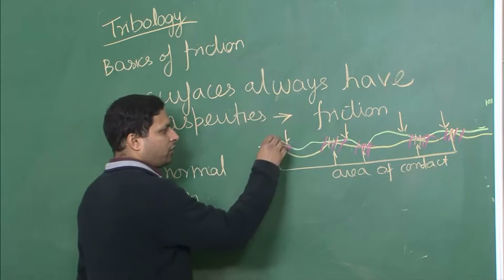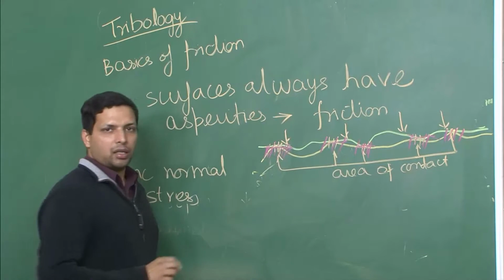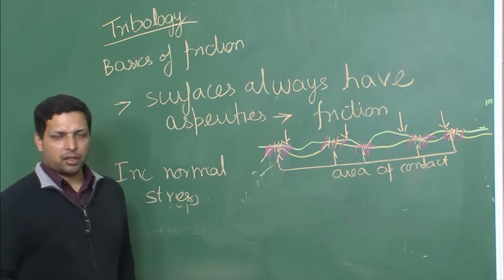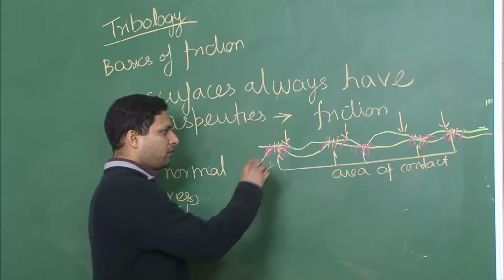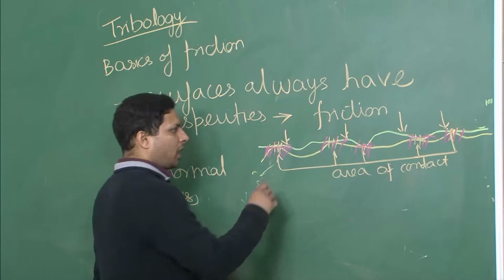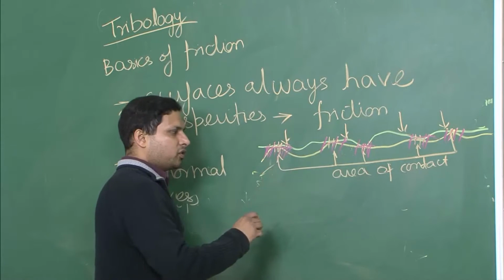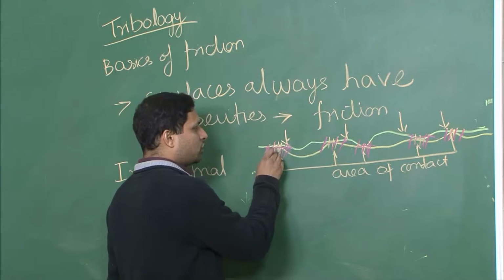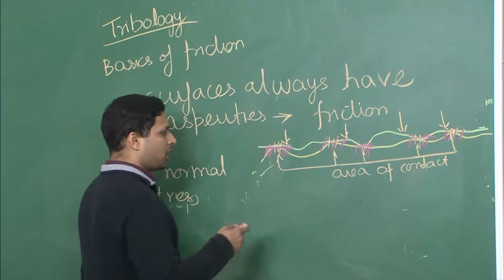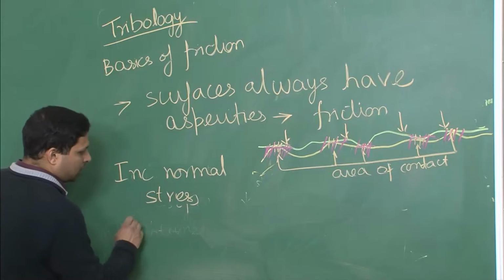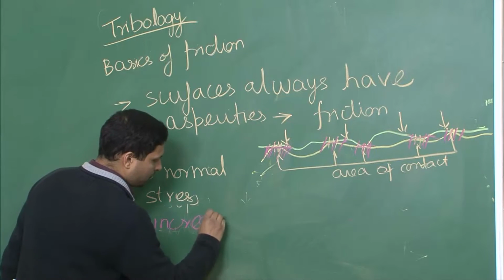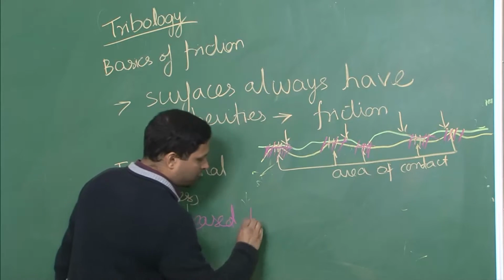When we have deformed, the area of contact has increased, and second, particularly in cases of metal, there may even be some small cold welding. So, the materials may get cold welded at places, or even if not, you can see that the work has to be done against a larger area. When you are trying to move this, it has to do work against a larger area, and that implies increased frictional forces.